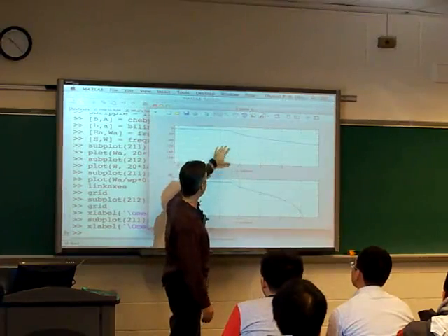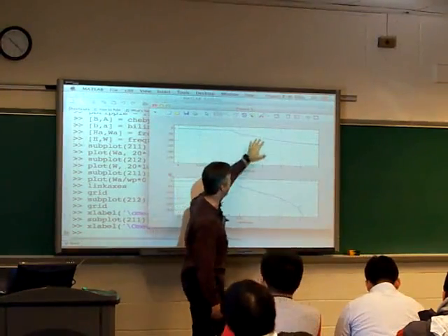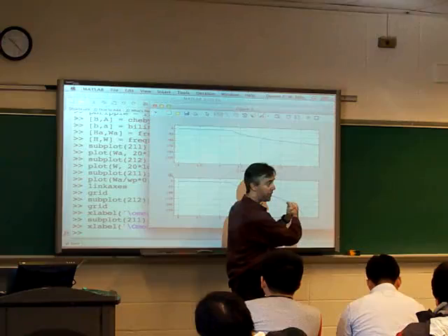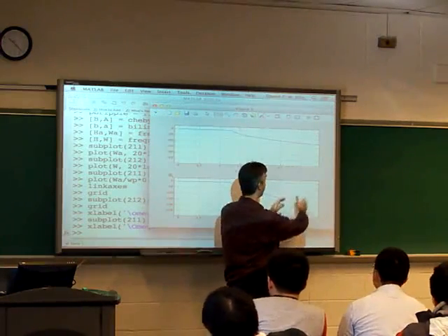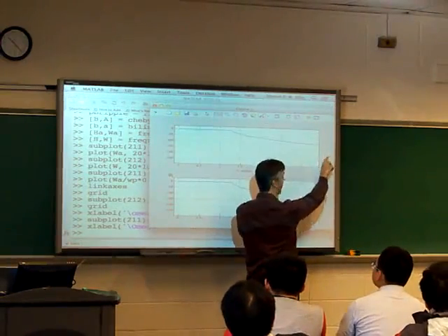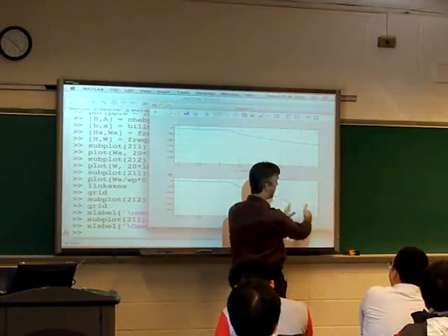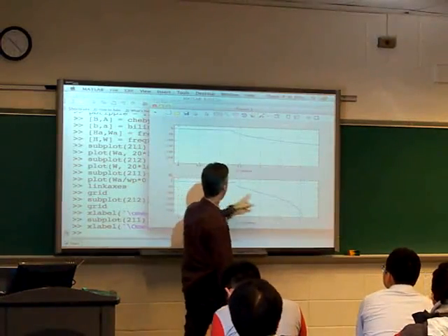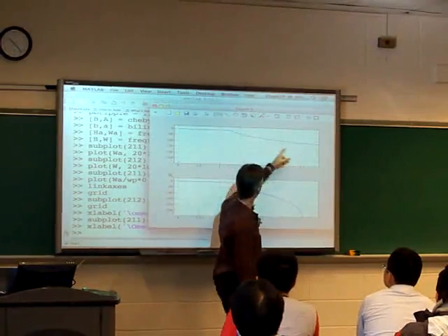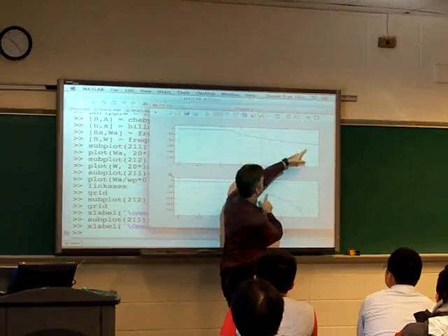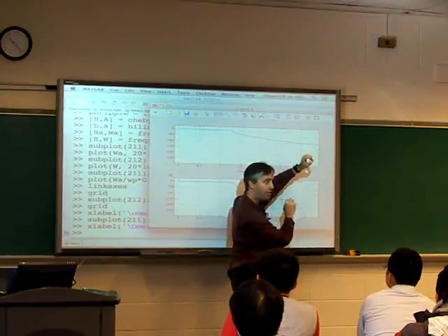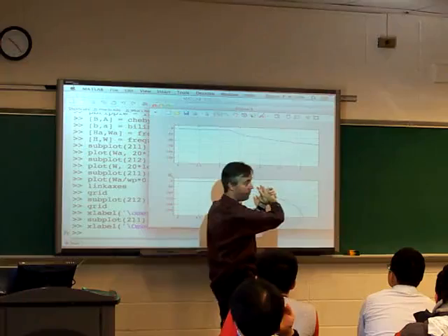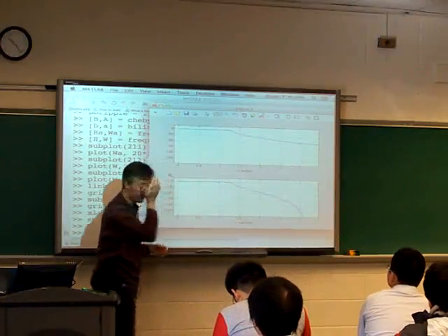So here we can see that they look kind of similar up here, but they look very different over here. And this is the effect of the arctan warping function compressing all the points for these higher frequencies into this finite range. If we actually take the point where the gain is at -100 dB, those are the same sort of values of the polynomial. If we looked at the phase at those points, they'd be the same phase. But the frequencies have just been warped by this arctan function.